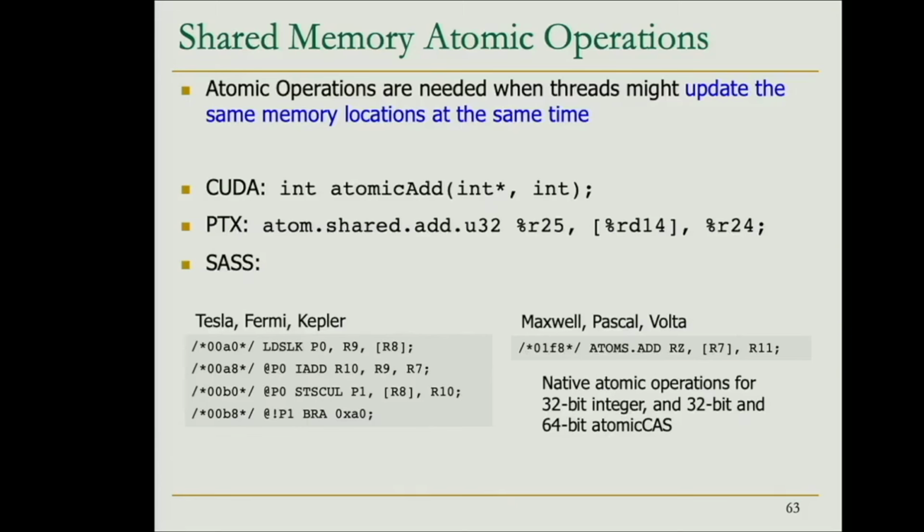If you look at the loop, what you have here is a load instruction, then an addition, then a store instruction, and then a branch, right? And also, you can see these P0 and P1, which are predicate registers. You remember, we have talked about predicated execution, right? So essentially, this predicate register is one single bit per thread. That's enough, one single bit per thread.